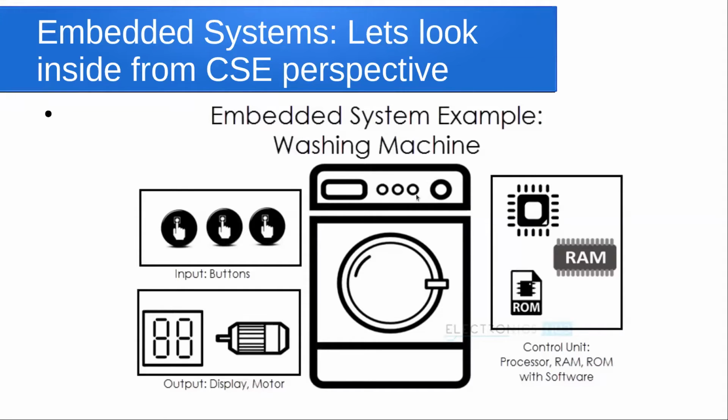So qualifying such a simple embedded system inside a washing machine as an Internet of Things compliant system, right? That is how we have it. So basically, an IoT device is an embedded system which enables the functionality of a much bigger system, but it is connected to the Internet protocol through a unique IP address that is allocated to this embedded system, right? So that is how we need to understand what an IoT node is, and when an embedded system qualifies to be called an IoT node.